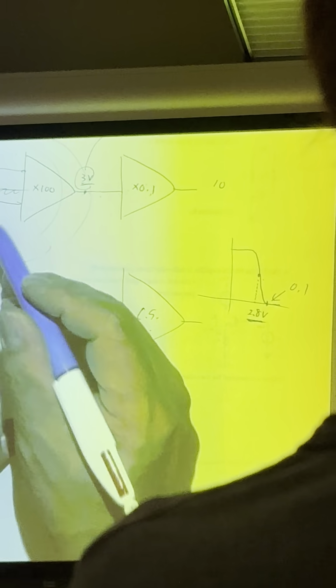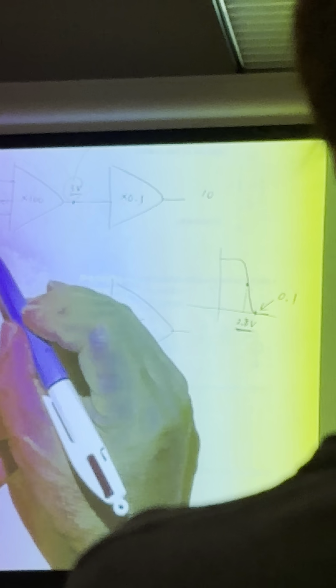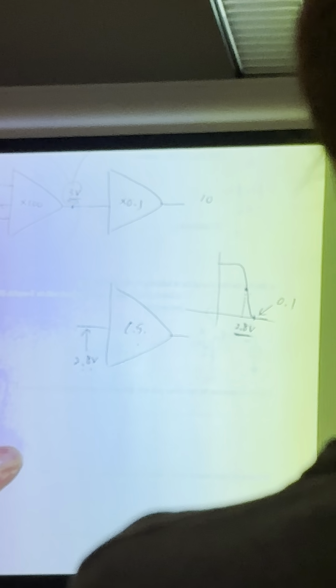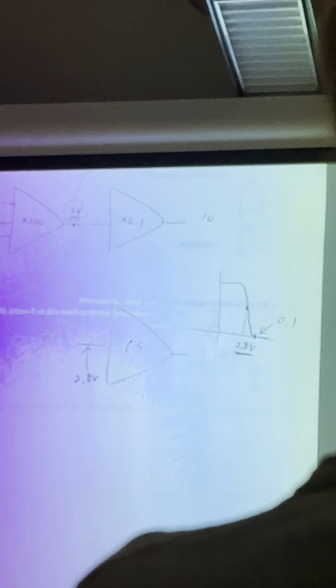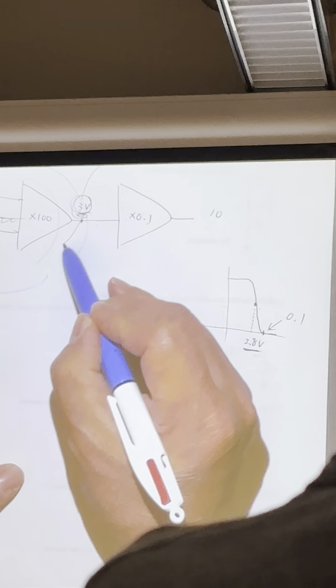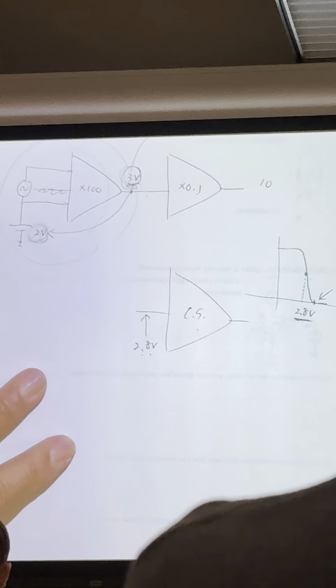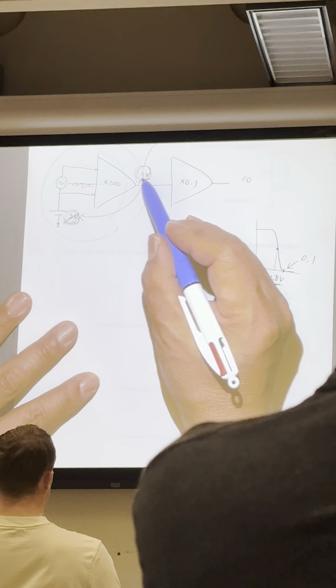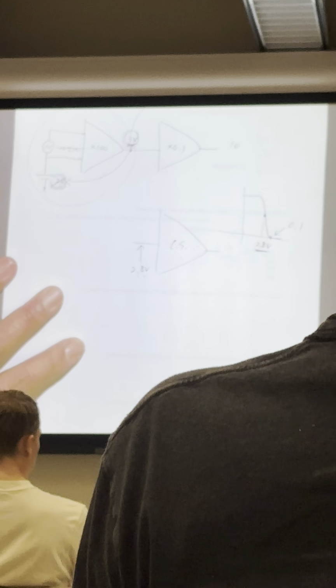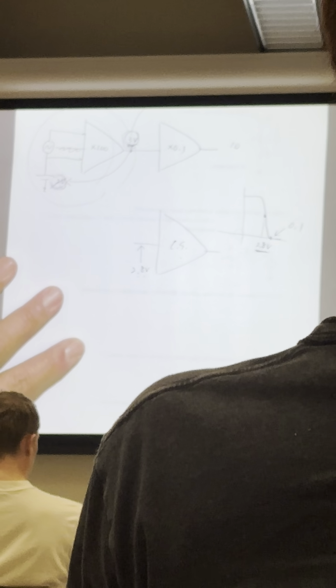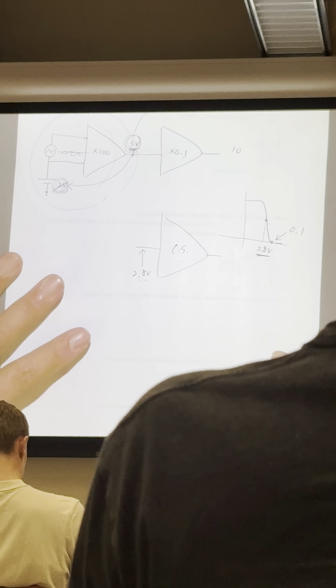When you change your input voltage, that doesn't help you. Your output voltage is not a function of your input voltage, so although you change this voltage, it's not going to change it. That's the advantage of your differential amplifier. The big advantage of your differential amplifier is that this voltage is not a function of your input DC voltage. So don't try to change this one to change this voltage. What you need to do is change the transistor size or biasing current. They should be changed, right? So that is one way. You don't want to do that.